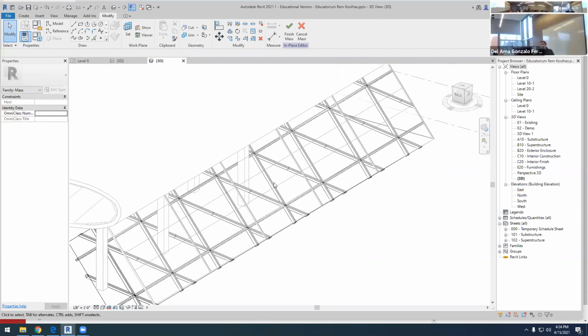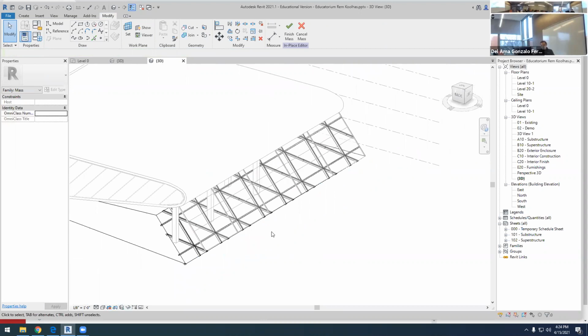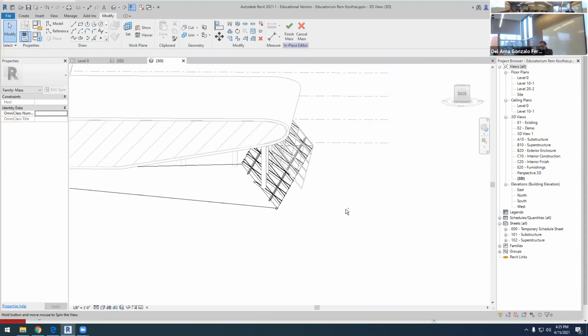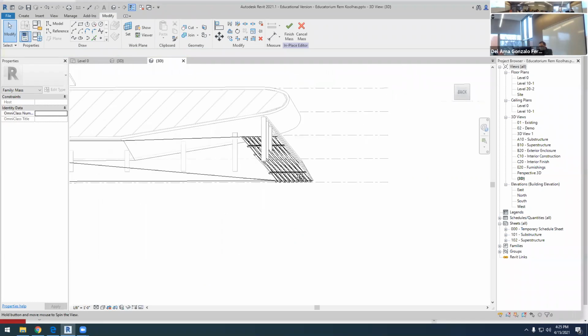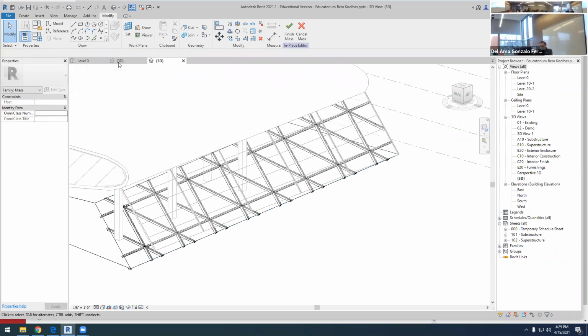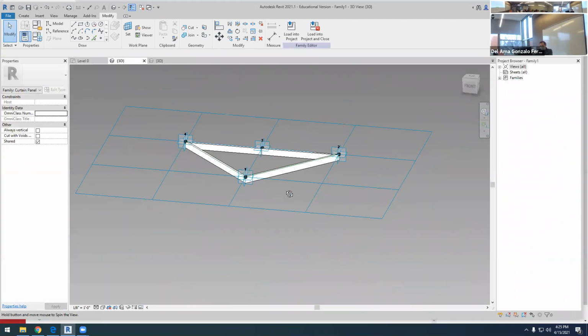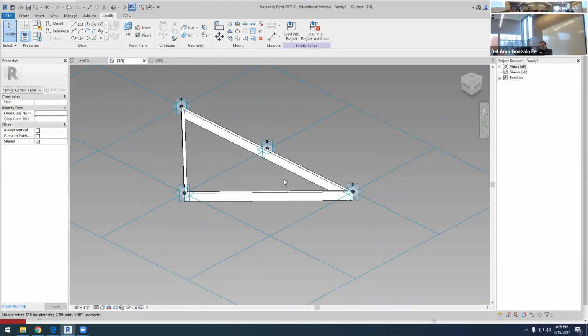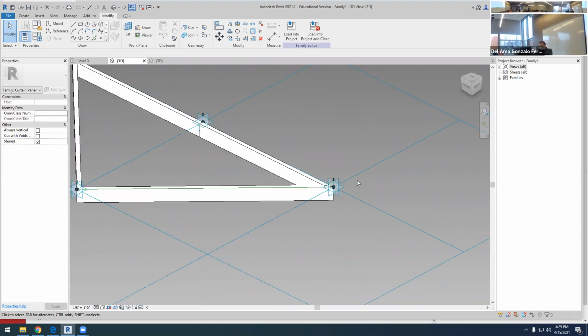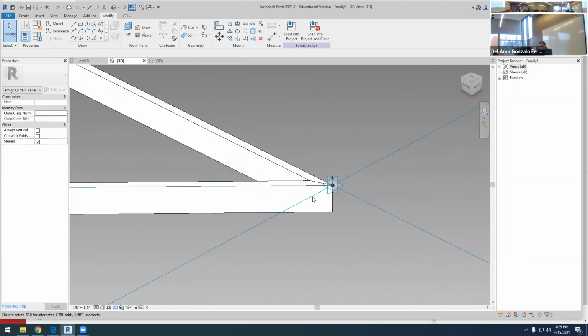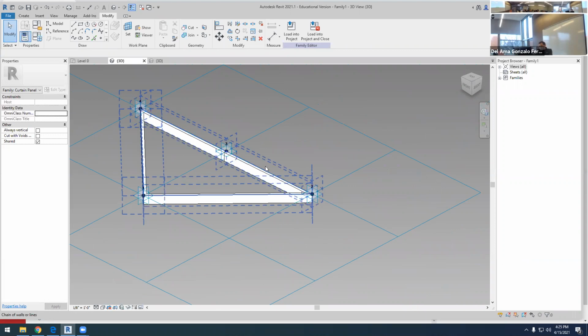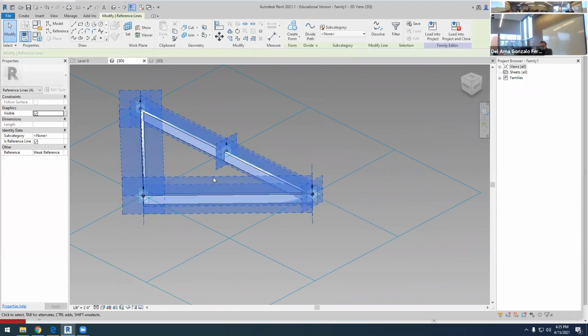Yes, okay. So try, but I think it's too advanced. So don't go crazy. You can do anything with Revit, but then you have to work with these families, and then you can create your own family. You can do something very simple like this. If you create a rectangle, and then you create that form all around this, and then don't forget that you have to create the glass as well to make it a curtain wall.